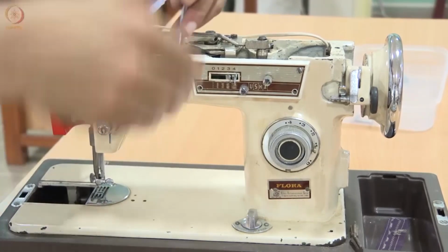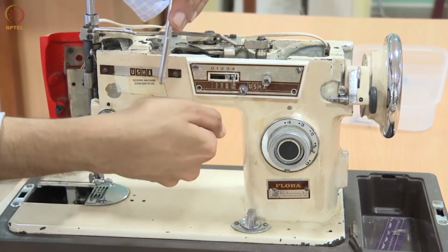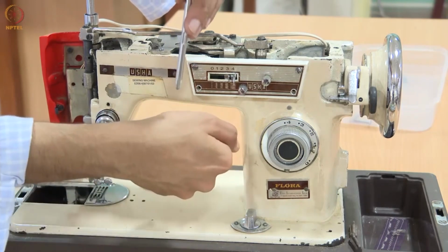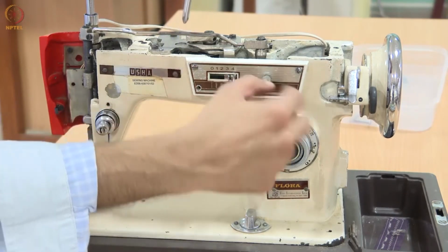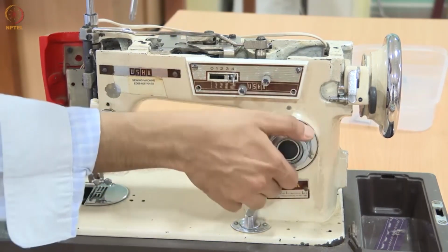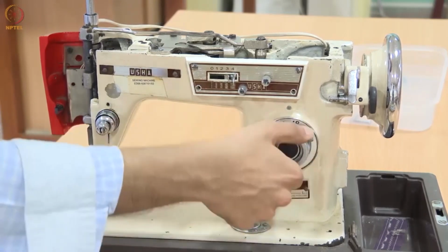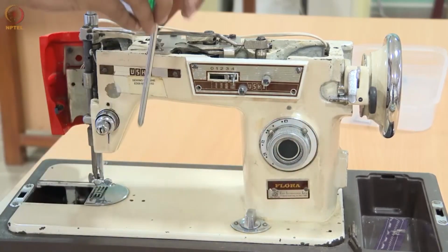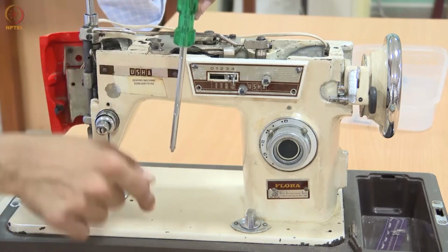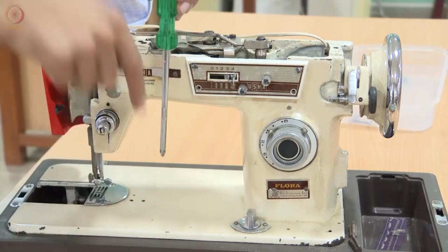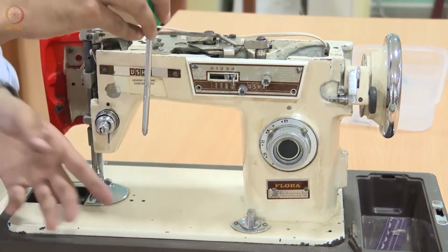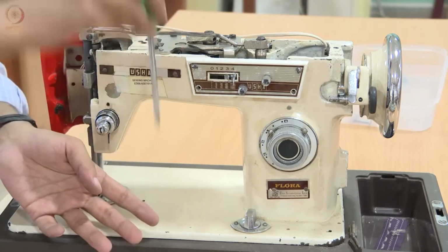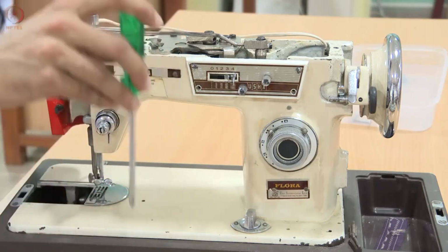Keep in mind the cloth is fed forward at a constant rate, and that pitch can be set by other levers here, right? Turning this knob sets that pitch rate, which is the pitch of the stitching. Now in addition, if the needle were to only travel up and down, it would be doing a linear stitch.